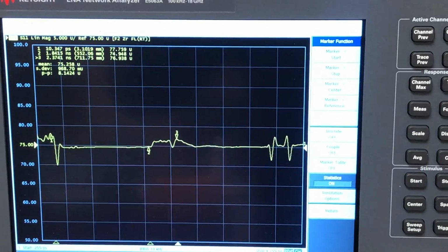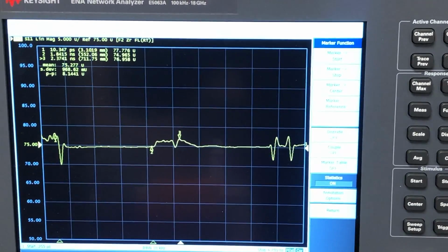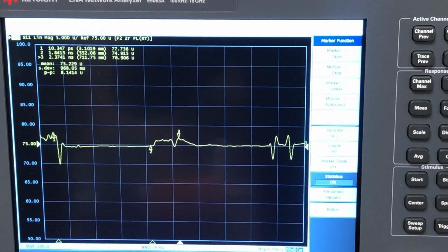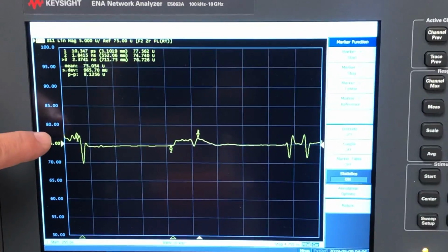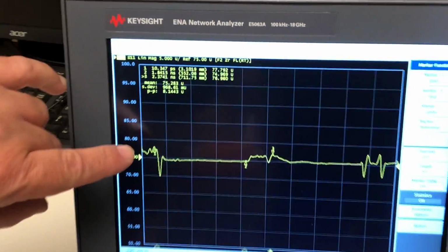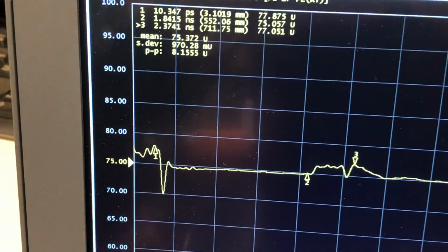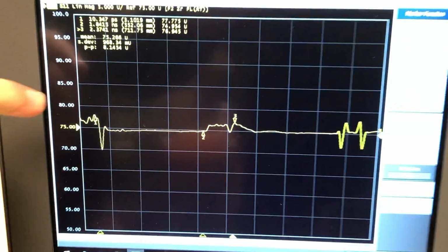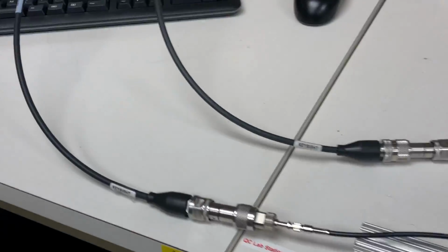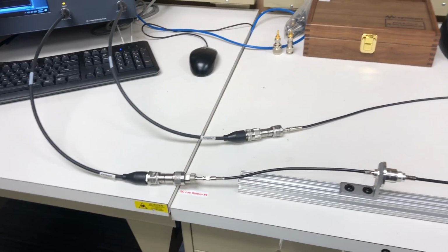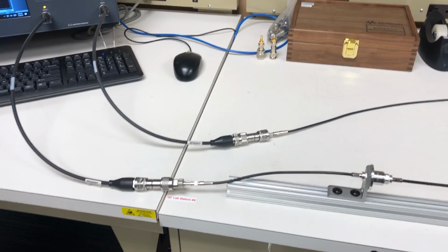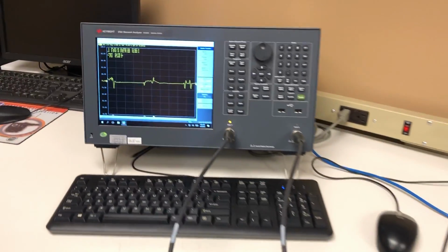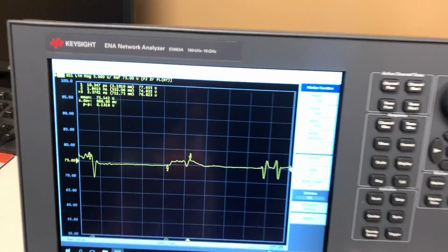Actually, we're looking up to past the rotary connection on here. Point number 1 on the scale is actually the beginning of the first HDBNC connector on the cable. So everything before that is actually inside the tester. And you can see that we have got a pretty stable 75 ohm impedance for the assembly so far.